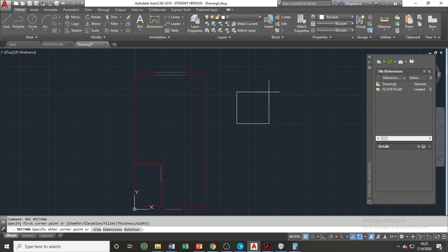To specify dimensions for your columns, quickly choose the Dimension sub-option by typing D and pressing spacebar. We will now enter the two dimensions of our columns. First, we will enter the dimension along the horizontal grid or the horizontal axis and press enter. And then for the vertical grid, enter your desired dimension and press enter as well.